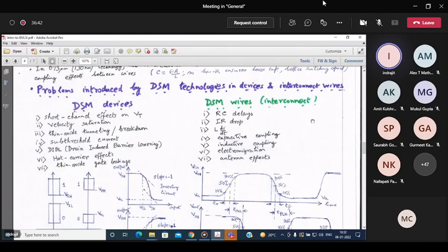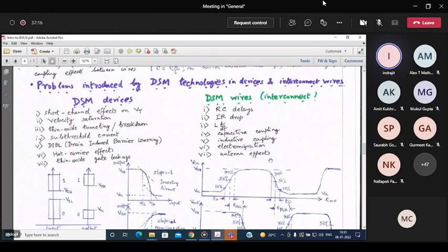That means the voltage drop between the gate and the underlying channel will grow, and due to the high voltage and x remaining the same, that means thickness remaining the same, dV/dx will be growing due to high field. It can lead to oxide breakdown. So the antenna effect may lead to oxide breakdown, and that will be undesirable. That means you want the device to remain off but current flows. So antenna effect is also undesirable, but how to take care of that, if time permits, we shall study.